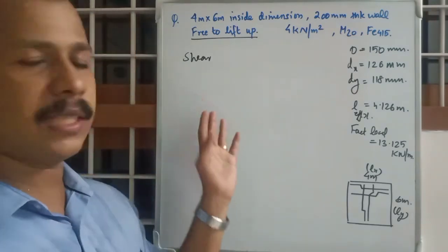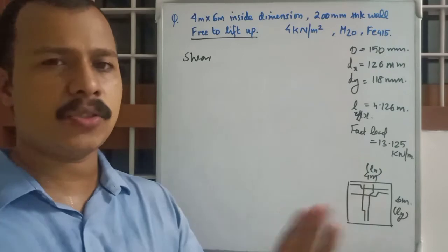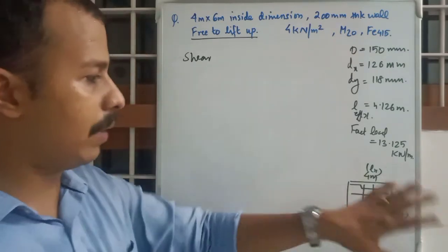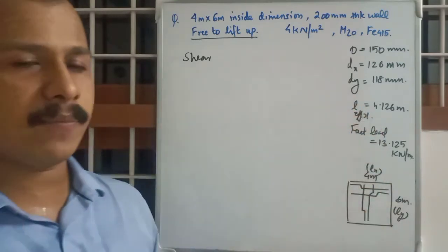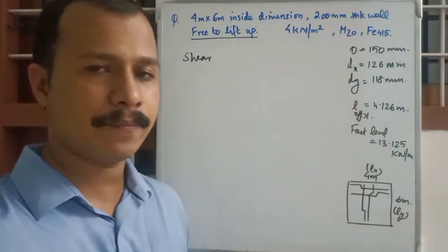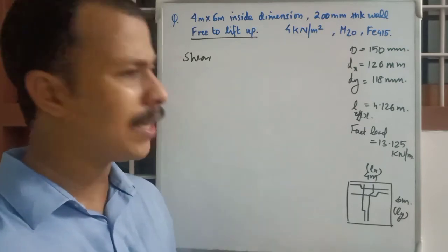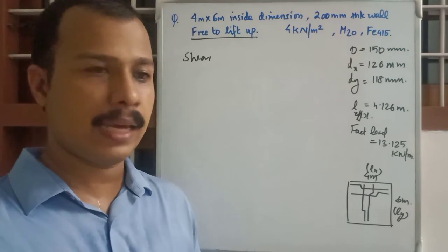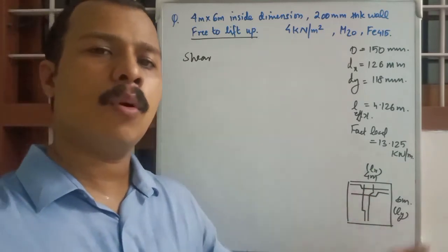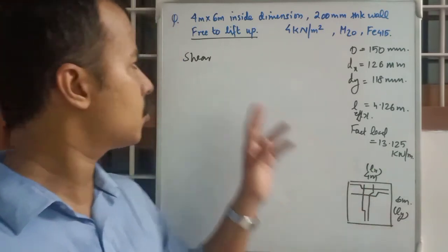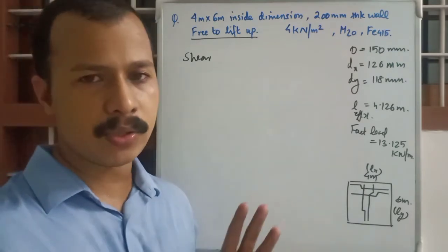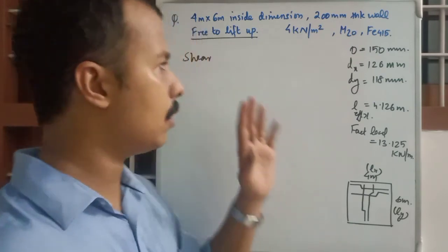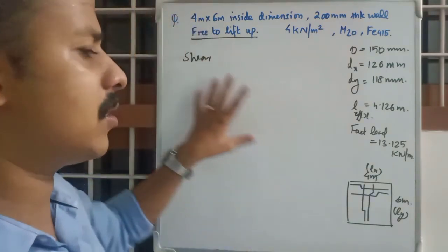Actually you will just write it as a heading and you will just write it off, because in shear reinforcement, as we have main reinforcement in both directions, shear stress will be too less. Okay, and for any two-way slab itself, shear stresses will be too less compared to one-way slabs. Of course we are providing more reinforcements into it. So shear is not an issue in a two-way slab situation. We have to decide for one-way slab, but in case of two-way slabs it's not an issue.